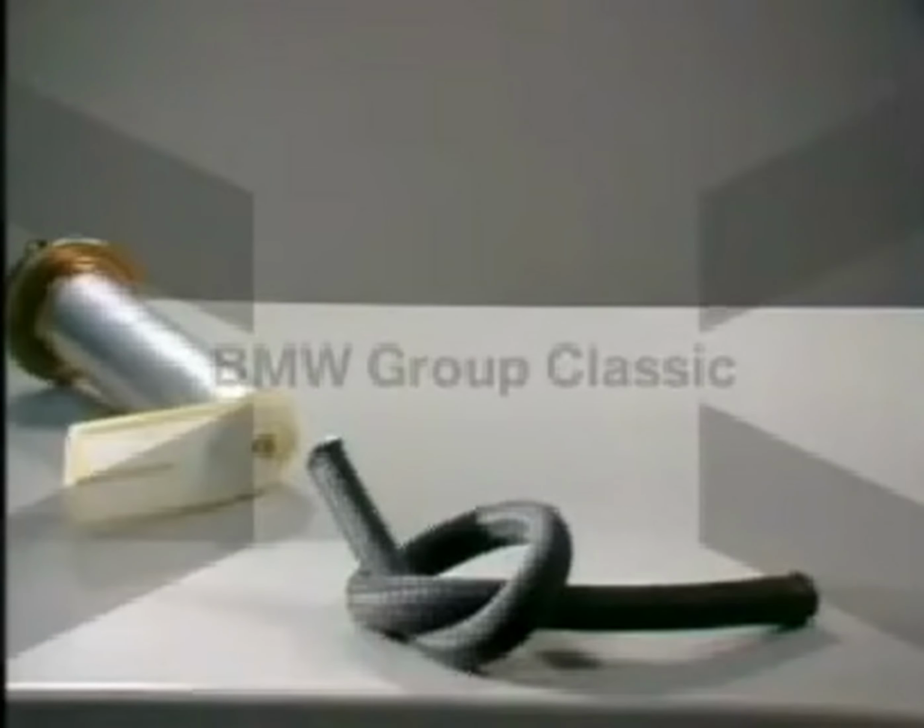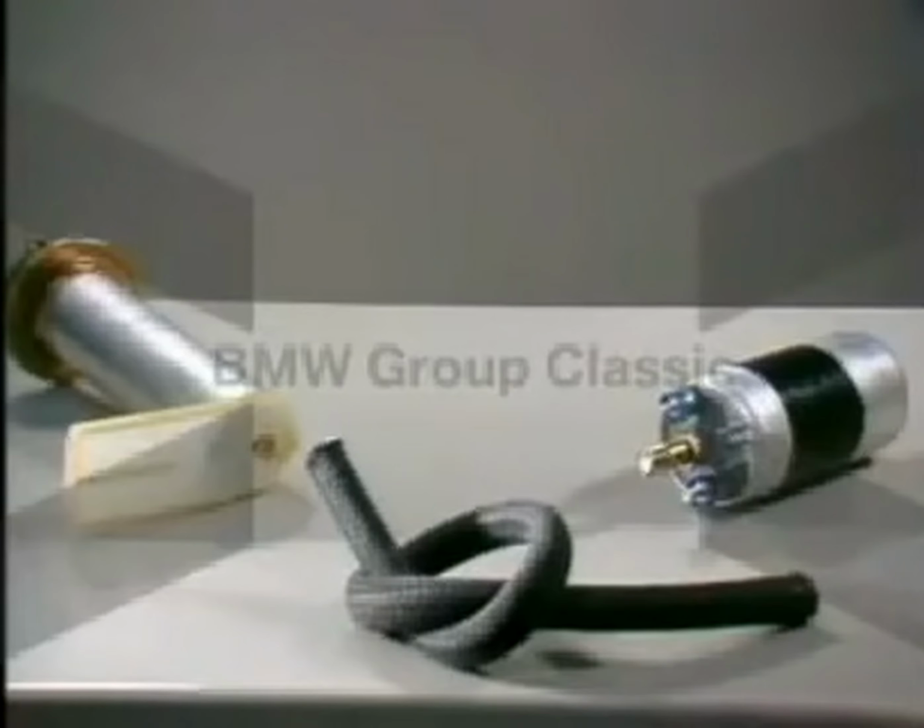If there is less than 750 cc of fuel in the container, the reasons for this could be the following. The fine filter in the tank unit is clogged. The fuel feed pipe has a kink. The fuel pump has a faulty electrical contact or is worn.